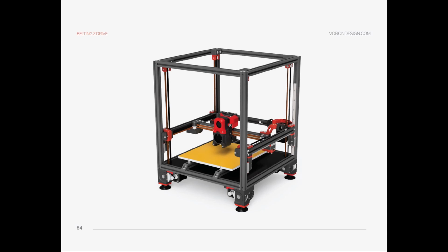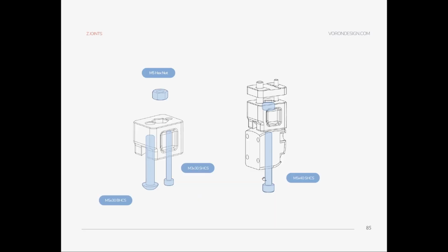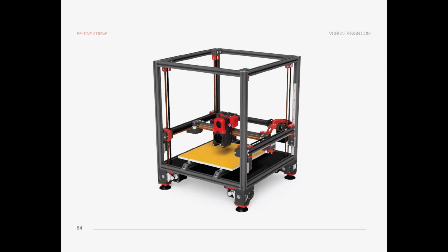in the back side and your steppers are off, you will see that the back of the gantry goes down a bit. So this joint is helping that movement. That's why you don't want to over tighten this one. There should be room for movement. After putting the gantry on your carriage, after that run your Z belts.